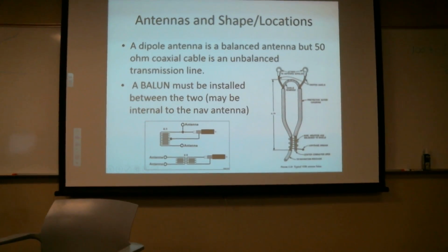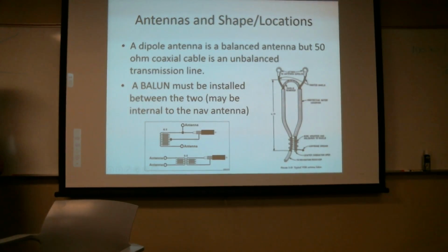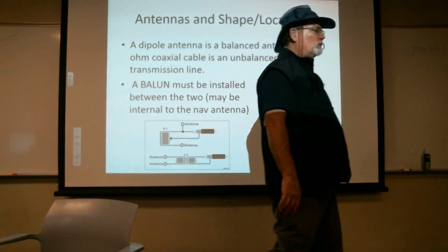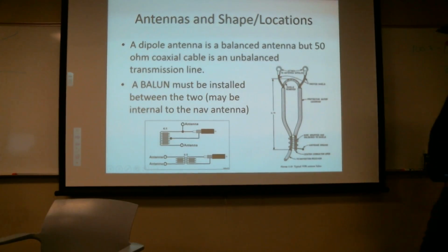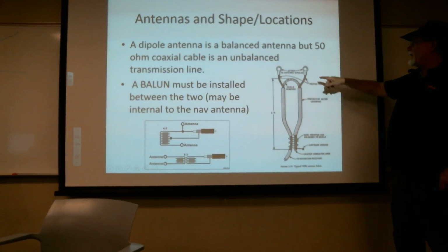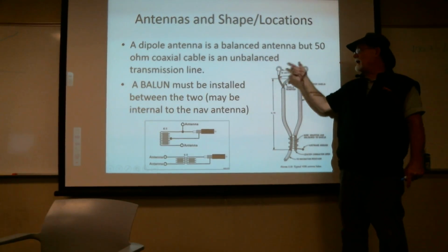So, a dipole antenna will be balanced, but if we convert it to a monopole where you've got a ground plane and the monopole, then you're going to have to come up with some way of balancing it. Now, this can be done with capacitors and inductors in the base, or if you've got an assembly like a single pole, just a single wire with a couple of nuts on it type antenna, then you can install ground plane to one and monopole to the other, or if I have a dipole, I can just attach each of the dipole to each of these.